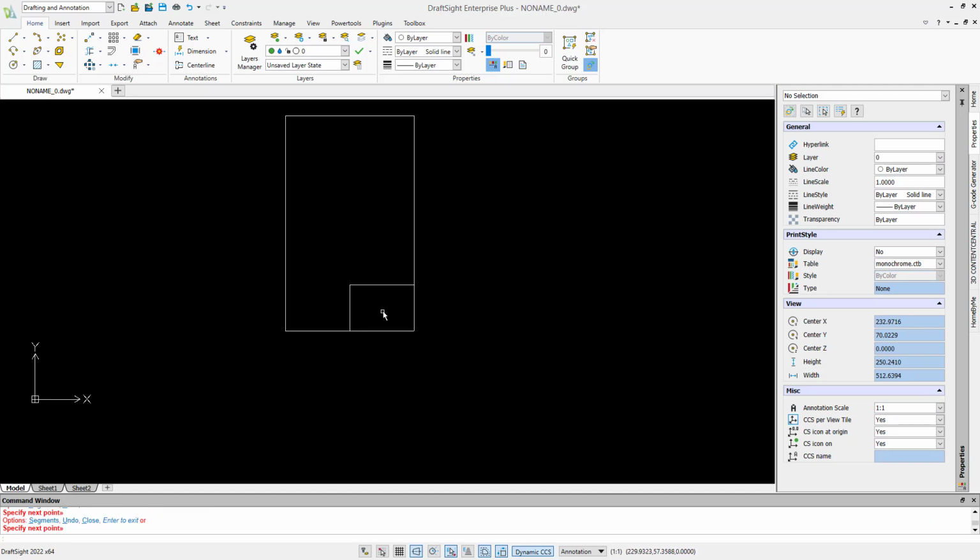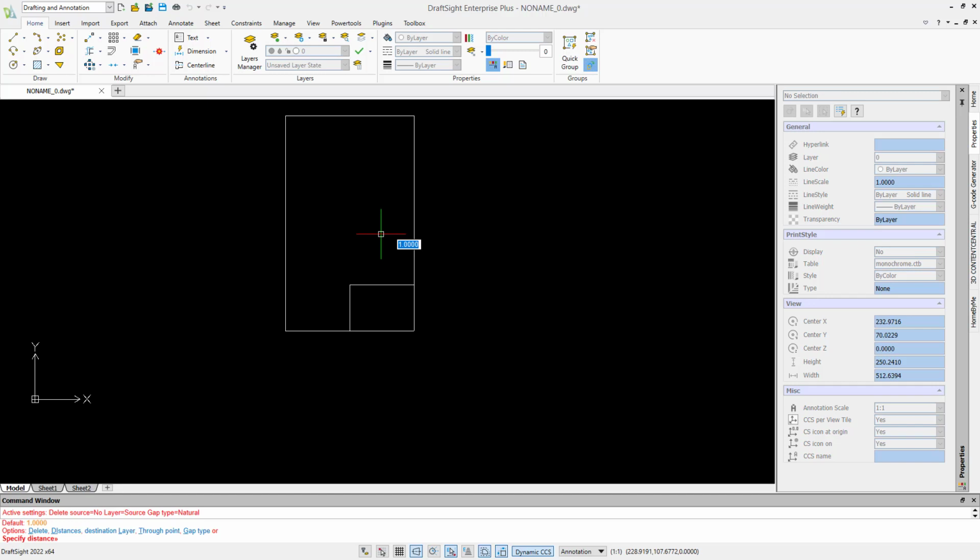I have already had two lines put in where I located the midpoint of the bottom portion of the rectangle and drew straight up 30 millimeters. I then continued to the right, connecting to the right side of the rectangle. Next, I typed in offset and entered in a 7 millimeter offset from the horizontal line inside the rectangle.